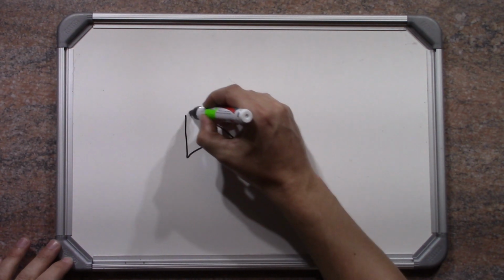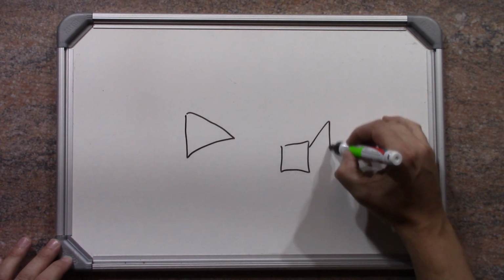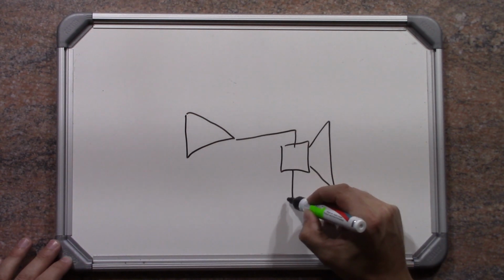So in its simplest form, a sound system would just be an amplifier and a speaker. The problem with this is that a speaker that will play the entire audio range would have to weigh nothing, be infinitely stiff and a reasonable size. Those are three conflicting properties and therefore you cannot build a speaker that will play the entire audio range. So you need to have different size speakers. You can have small, stiff speakers called tweeters and then big, hard, heavy speakers called woofers.